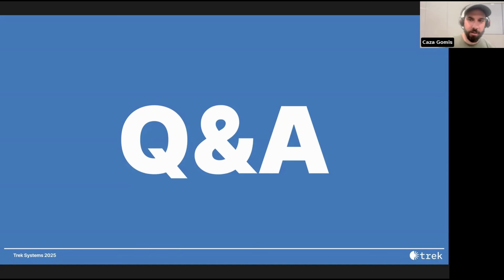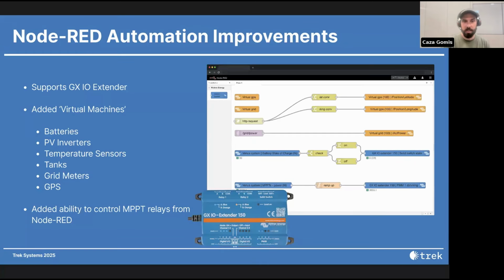Yeah, and one thing that you reminded me of, TJ, that I'd like to bring up before we close here: with Node-RED, we were brainstorming earlier about some other possibilities, and with the PWM function being controllable through Node-RED, you could set up an automation that, when you hit a certain time in the evening, your lights start to come on. You could have them ramp up in terms of dimness. As it gets later, maybe you could automate dimming as well. So 8, 9 o'clock rolls around, you've got an automation in place where your lights will automatically dim to 20, 30%, whatever. That ties back into what's possible using this Node-RED capability alongside the IO extender.